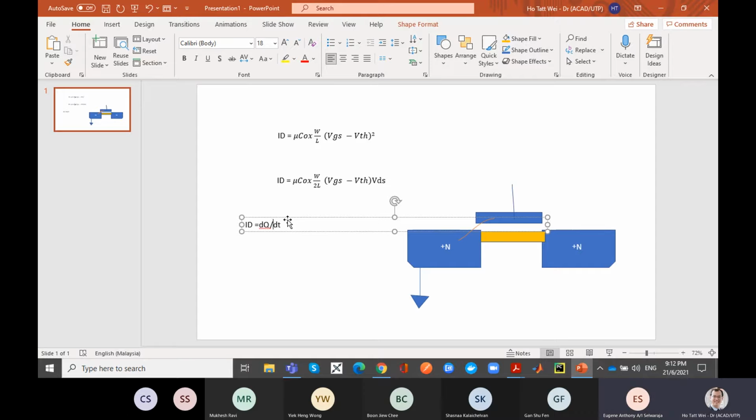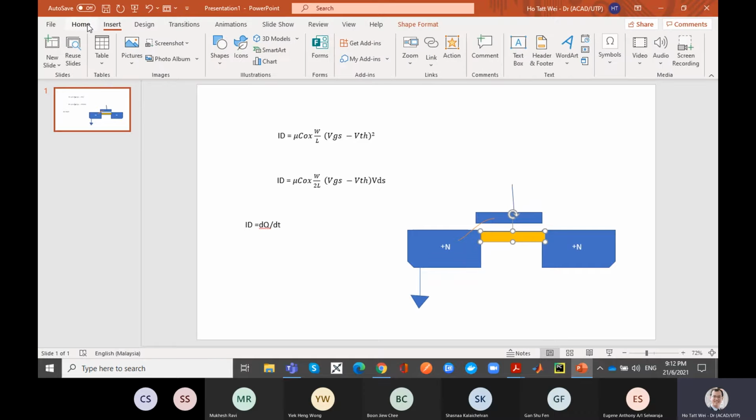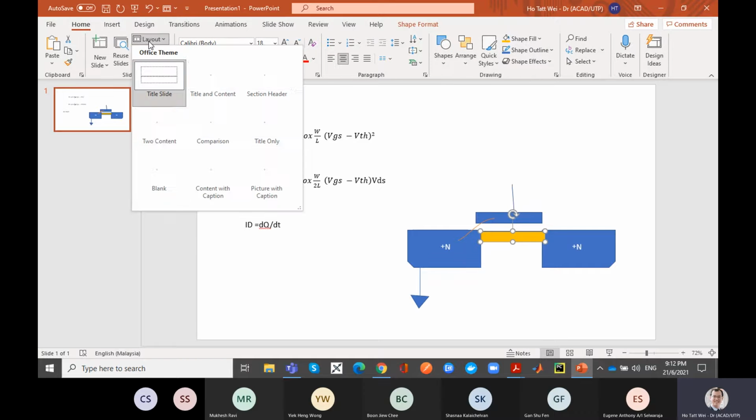Yeah. So again, we need to understand this relationship, because this relationship tells us all the levers we have to increase the current in the MOSFET. Ultimately, the current will also be dependent on VDS, that is the voltage from here to here. But in saturation, what actually happens is there's something called pinch off.